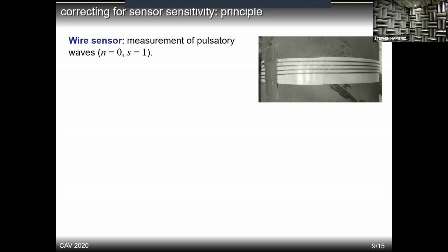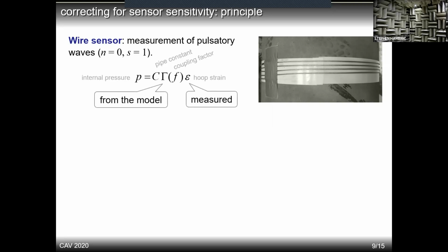Now, this sensor is usually hand-mounted by applying a tension during winding. If the tension force is not uniformly applied to all sensors, a change of sensitivity between sensors may take place, which in turn may lead to unusable results.